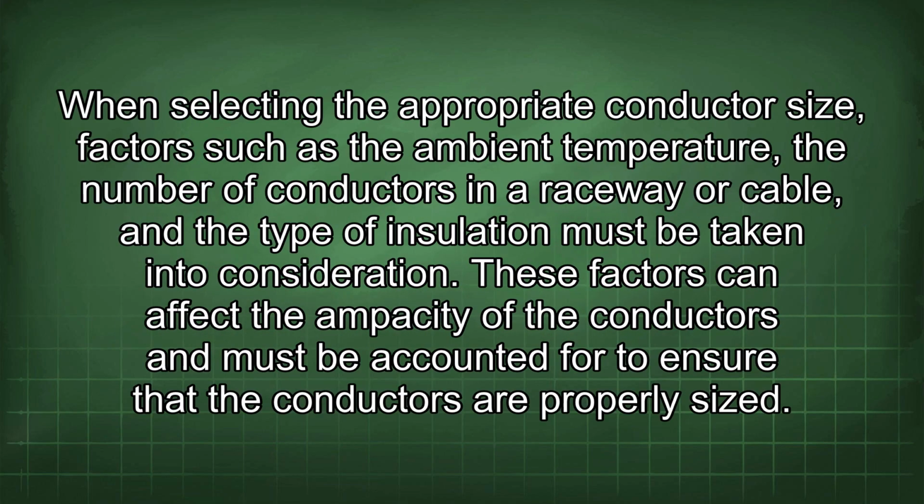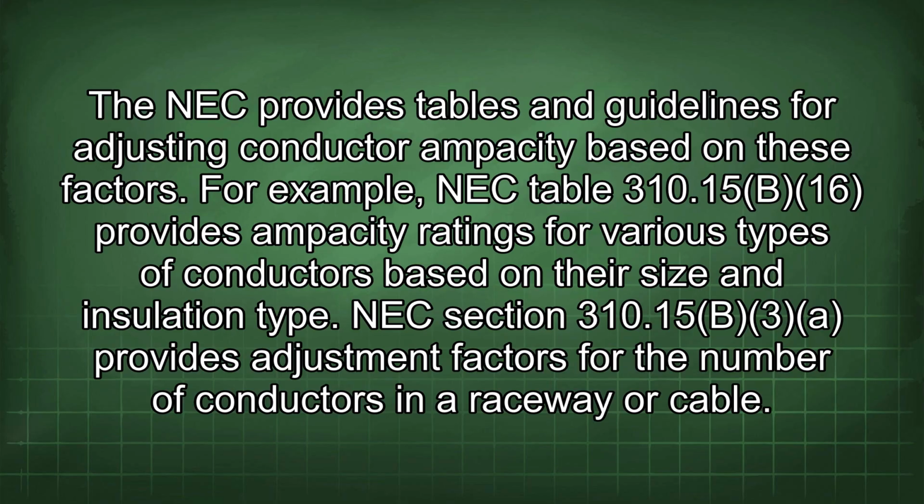When selecting the appropriate conductor size, factors such as the ambient temperature, the number of conductors in a raceway or cable, and the type of insulation must be taken into consideration. These factors can affect the ampacity of the conductors and must be accounted for to ensure that the conductors are properly sized. The NEC provides tables and guidelines for adjusting conductor ampacity based on these factors.